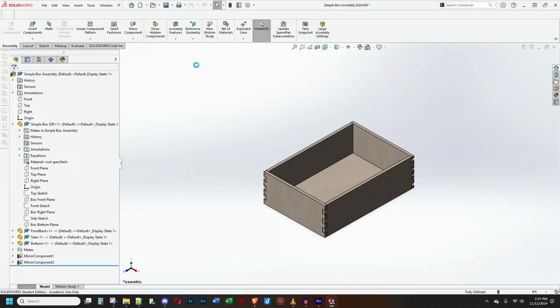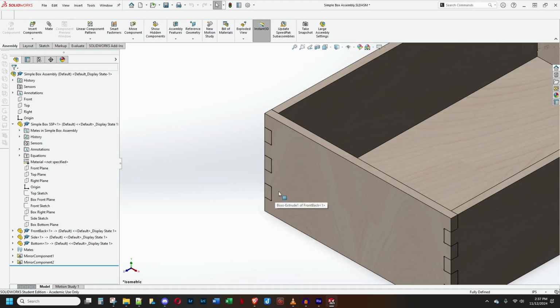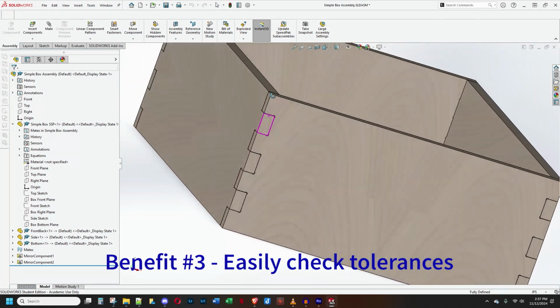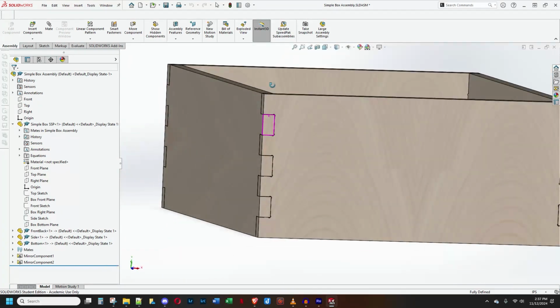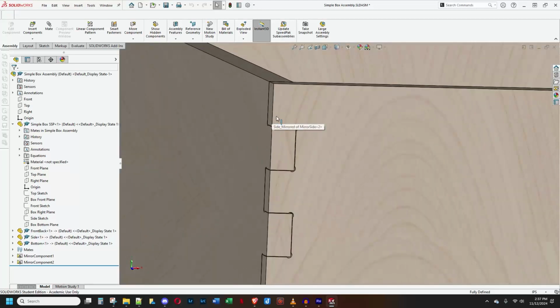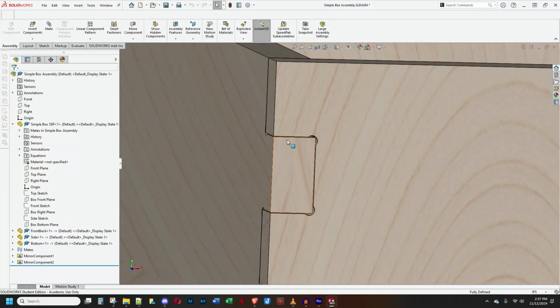It's not just the dimensions that you can check. You can also check this idea of a tolerance. The tolerance can't be 0, or the parts won't mate, because both the edges of both parts would be occupying the same point in space, so you've got to give them a little bit of a gap to slip together. And in my woodworking, 1/128 of an inch, which I realize is ridiculously small, seems to work pretty well for me. But how do I know if I've got it applied?